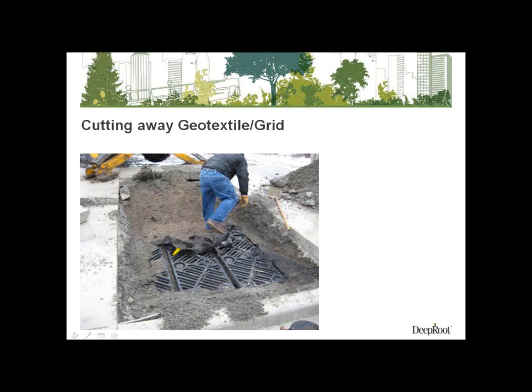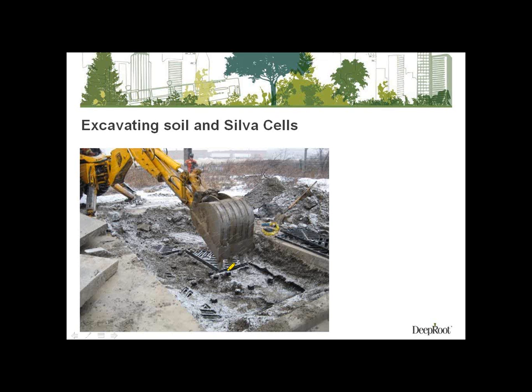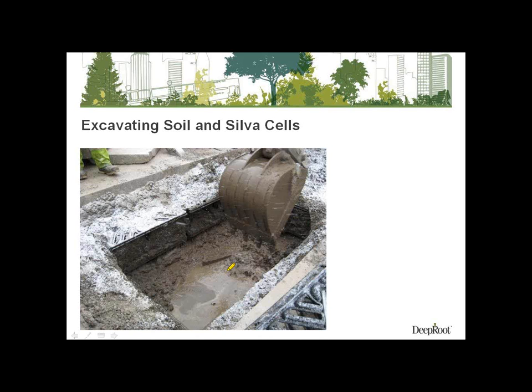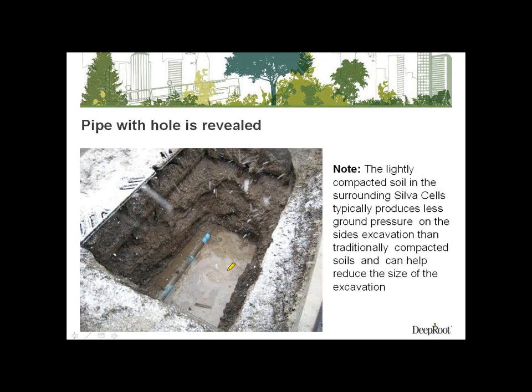Now here, as we discussed previously, you have the option. You can unscrew these decks and salvage them, and you can hydrovac or work your way around these frames and remove them and salvage them. But that's not the option we went with here. This was to simulate a broken water main or a ruptured gas service or something that needs immediate attention where time is of the essence. So in this demonstration, we just dug right through the Silva Cells. The excavator just dug through them and loaded it all out just as they were digging the rest of the excavation out. Eventually they exposed the pipe and got to a point where the repair could be made.